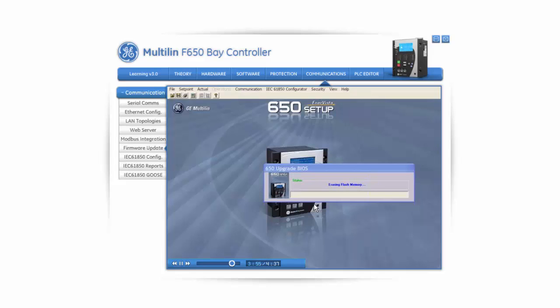Up to now, no important change has been made to the relay or operating system. The memory upgrading process has just been prepared. This process can take some time, during which a progress bar is displayed. In the case of having some problems with the Ethernet connection, this process could be blocked. This is most likely to happen when above the progress bar, the label Sending File Image _ Kernel appears.